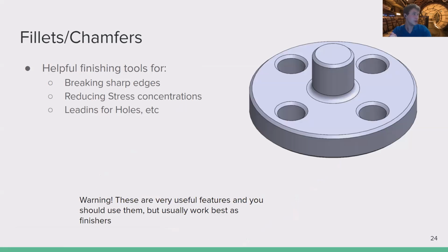All right, now we also use fillets and chamfers all the time. These are really helpful finishing tools. Chamfers are the angular one. They just add a little knock off the corner. And then fillets are the curvy one.